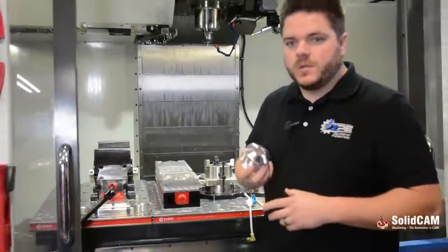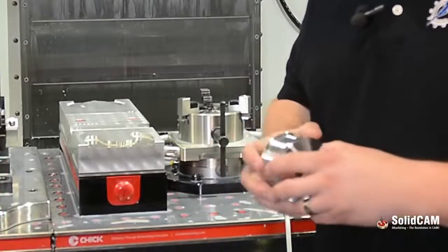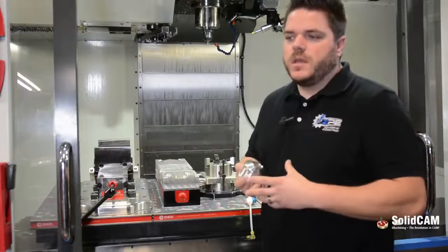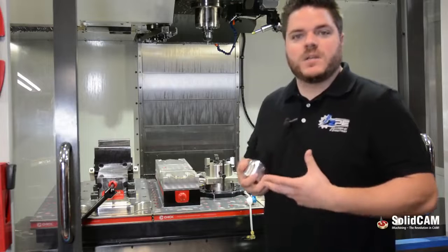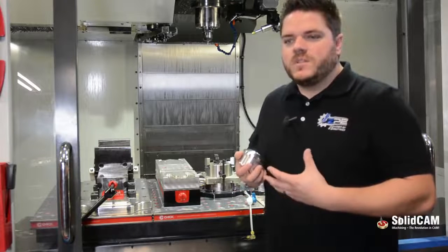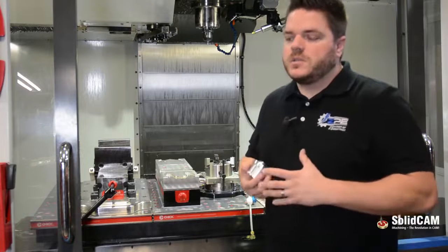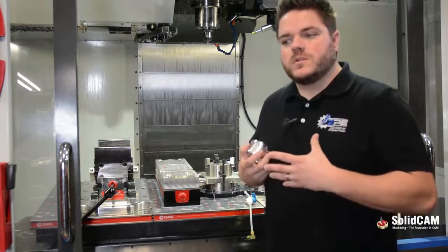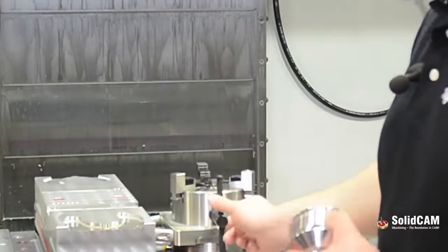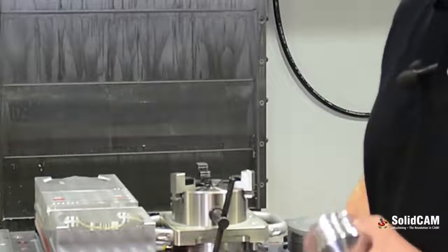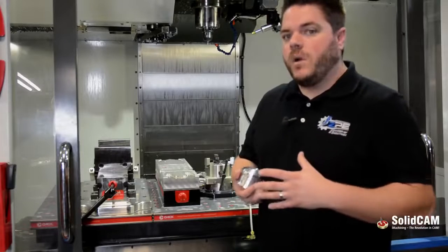So right here we have a good example of one of our parts. When we make our parts, we have customers order these parts in sizes of basically 25 thou increments sometimes. So to have a fixture to fit all of our parts on the inner diameter and the outer diameter is somewhat challenging. So sometimes when we get specialty orders for unique sizes, we will resort to using an automatic 3-jaw chuck, which naturally doesn't carry a real good repeatability in the X and the Y.